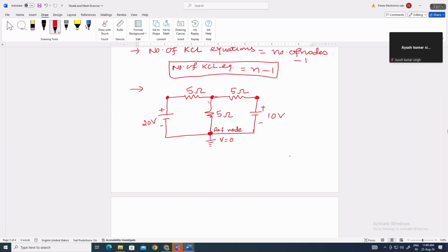यस सर. और उसके बाद हमको KCL अप्लाई करना है. तो फॉर द सिंप्लिसिटी, we will not take those nodes where current is going same. यहाँ पे जो करंट फ्लो करेगा, क्योंकि दोनों सीरीज में कनेक्टेड हैं, तो करंट डायरेक्शन सेम होगा, करंट का वैल्यू सेम होगा। यहाँ पे भी करंट का वैल्यू सेम होगा, राइट, इन दोनों में। तो ये वाला नोड को और ये वाला नोड को लेने का कोई मीनिंग नहीं है, हमारा अननेसेसरी इक्वेशन ज़्यादा होगा। सो केवल एक ये प्रिंसिपल नोड को हम एज्यूम कर ले रहे हैं और यहाँ पे वोल्टेज हम V मानेंगे, तो इससे हमारा काम हो जाएगा, राइट।